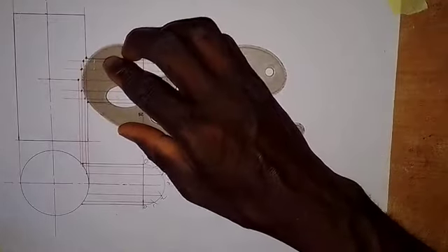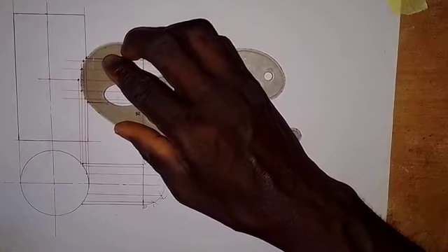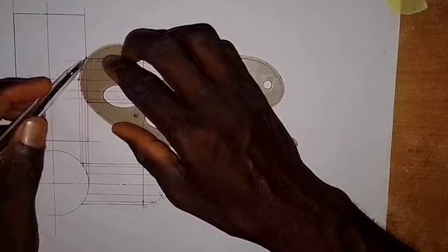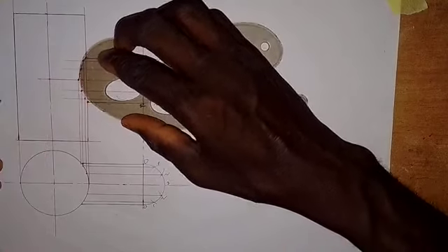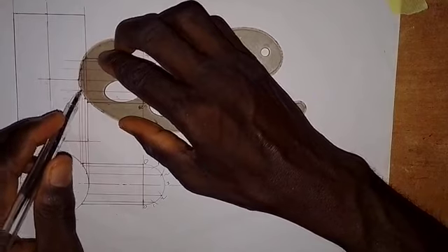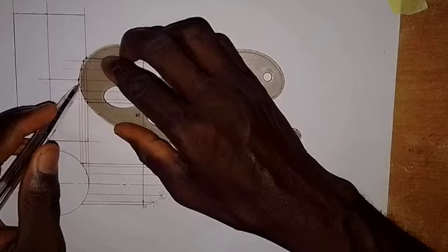Okay, so the next thing that we are going to do is to draw the curve of intersection, having gotten these points. With the French curve, we bring it to this point. Looking at what we have here, we have these points well arranged. So we are going to join them together using the French curve as I'm doing it here. We set it here and we join the points together like this, as you can see. Alright, so we have produced the curve of intersection of these two cylinders that intersect each other at right angle.